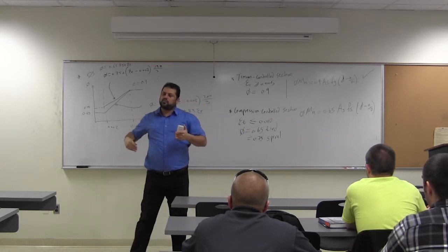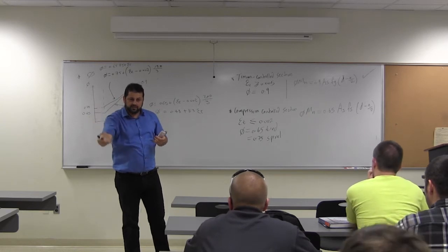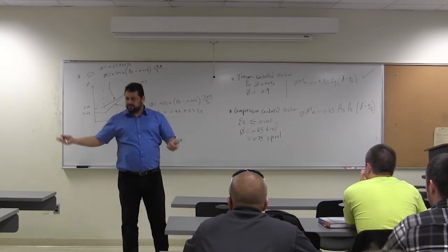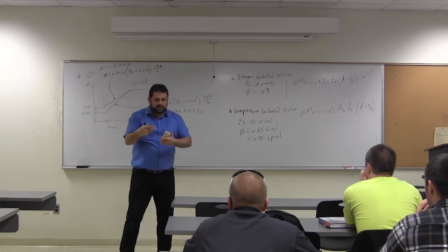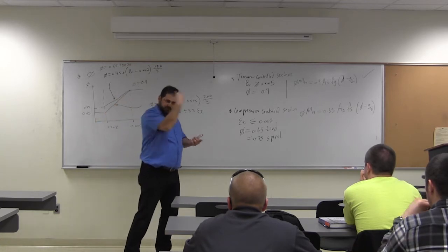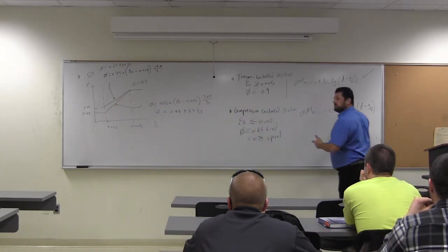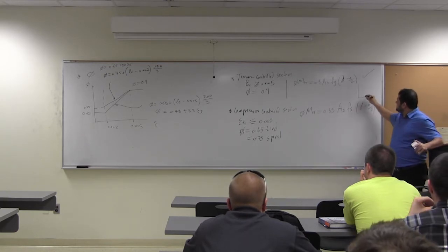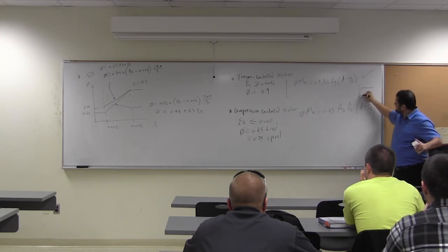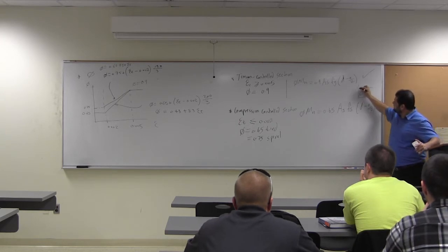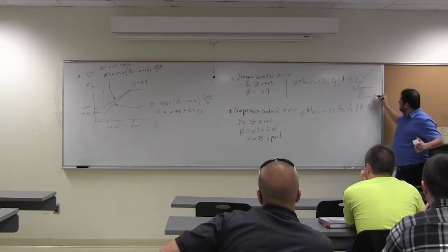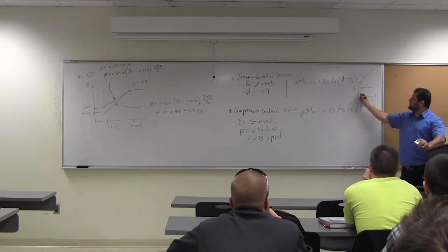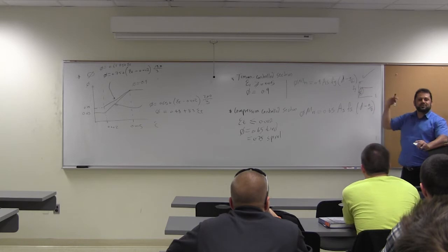Now, anytime you need one more equation, more than the available equilibrium equations, what do you do in mechanics? We go into something called compatibility, right? We go to the strain distribution, or can we relate the deflections together? Compatibility, strain distribution. We get this from there. How? Because we know the steel is in this behavior. If this is the stress-strain diagram of the steel, elastoplastic, we are here. It did not yield. This is the idealized stress-strain diagram for steel. This is what we use for the design. The stress is somewhere in here. It means Hooke's law is valid.